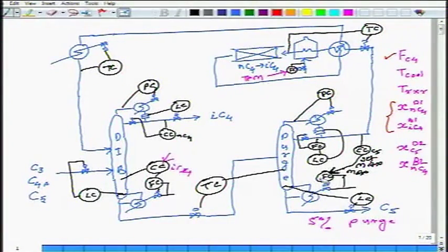Yes or no? Again, repeat. The case is very simple. If I am using a manipulated variable to control a controlled variable, when that manipulated variable saturates, it reaches its limit, then the control of that CV is lost. If MV saturates, CV is not controlled anymore; it floats until MV becomes unsaturated again. Yes or no? That's very clear.